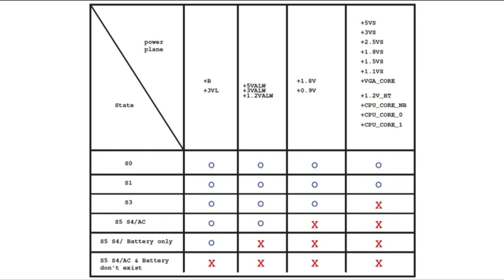But for the RAM, as you know, there are many types of random access memory: DDR1, DDR2, DDR3, DDR4, DDR5, etc. So this power here, 1.8 volt and 0.9 volt, is for DDR2. Okay, so the RAM has basically 2 kinds of power: the main power and the power for VTT, or terminals.